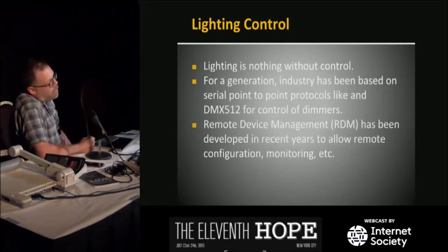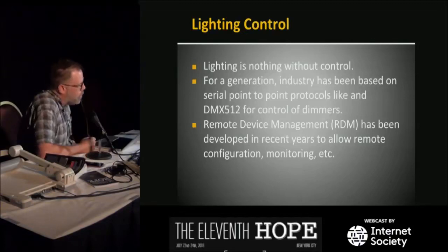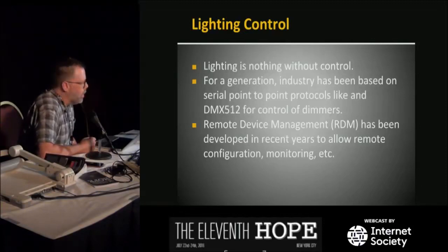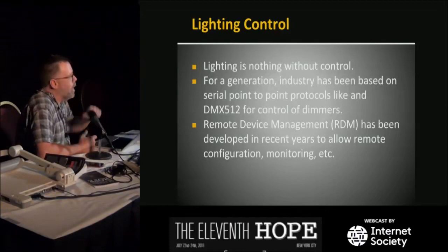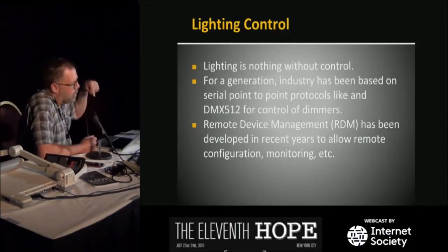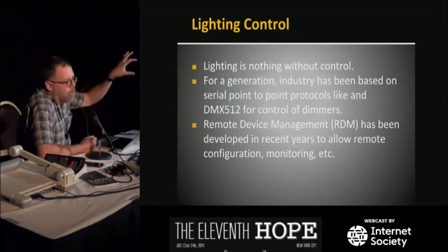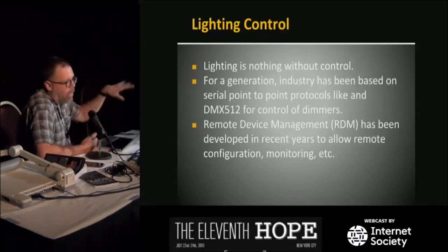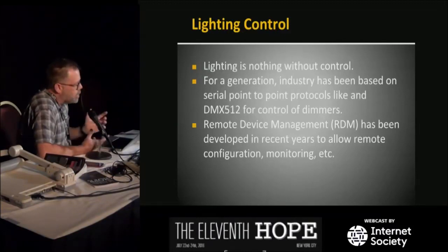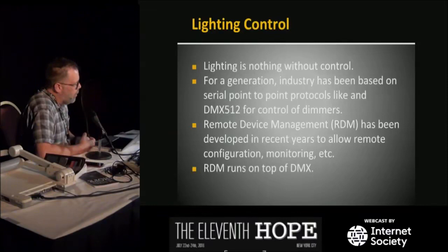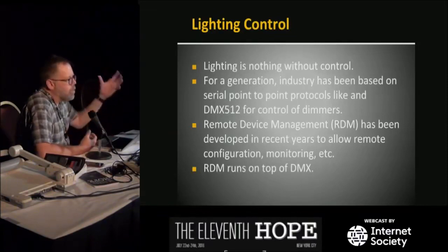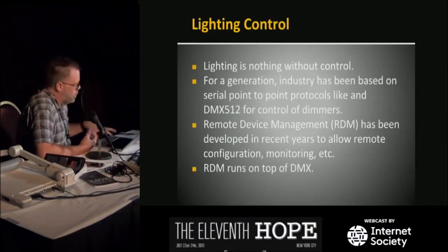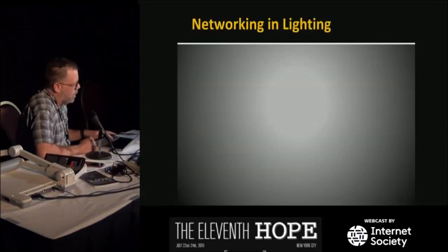So also in the last about 10 years, there's another protocol called remote device management that's been coming around. That rides in the back of DMX, allows you, for example, if we had a moving light over here, we could set some parameters in the moving light without having to get a ladder out and push some buttons on the back. Also, we can monitor lamp hours and things like that. So that's come in. It's finally starting to catch on a little bit. That's a long story, but that runs on top of DMX. So that's sort of where we were prior to networks, although RDM's sort of after that. The timeline's a little bit simplified here.